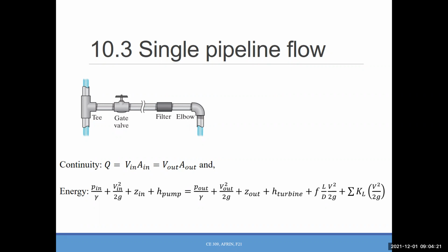The reason I gave you this table is that usually for head loss, we can have broadly three different types of problems. For type 1, everything is given, we just need to calculate head loss. For type 2, we need to calculate the discharge. And for type 3, which is the design problem, we need to determine the size of the pipe.